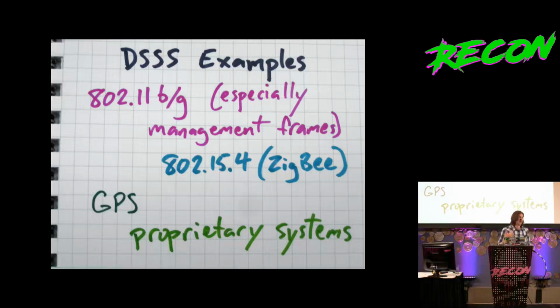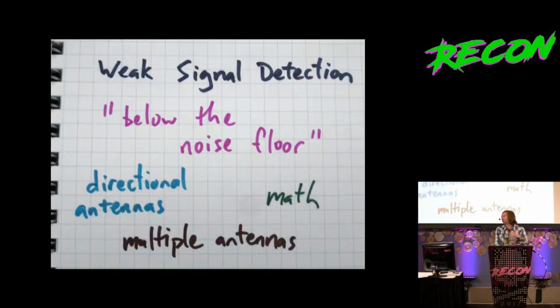And this is where I think these systems are interesting from a reverse engineering standpoint. Sometimes you might be interested in picking up a signal. You might not know what it is, but you can maybe detect a signal that people thought would be difficult to detect. And you can reverse engineer the chip sequence. Because if you know the chip sequence, then you can decode the transmission. But you need to have the chip sequence, which is a pseudo-random sequence. And these systems can be kind of buried in the noise.